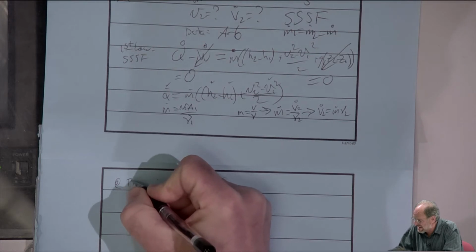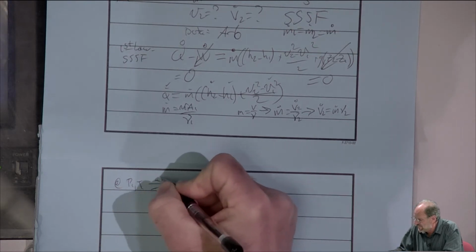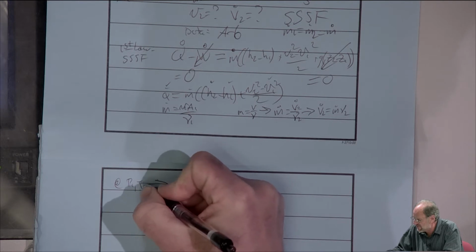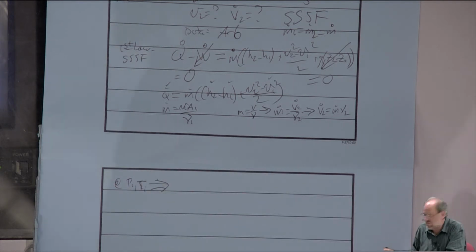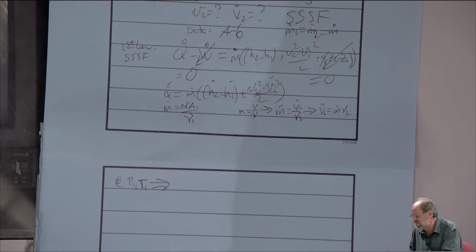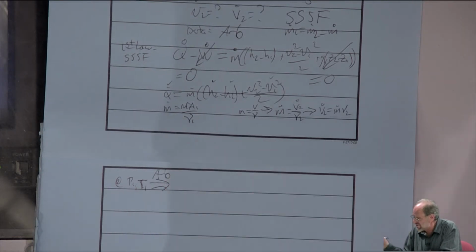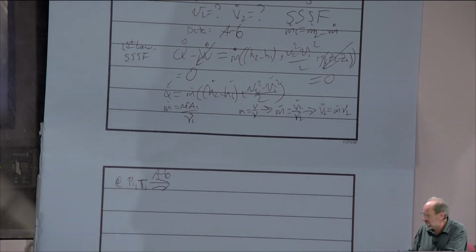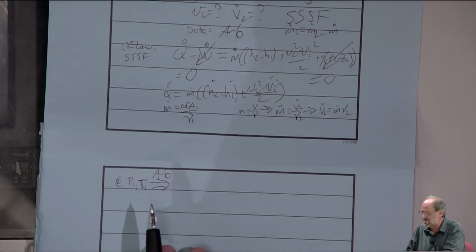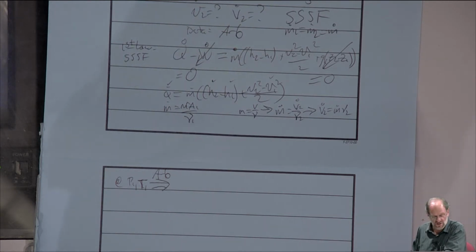We'll start at P1, T1. We're told that it's steam, although if you don't believe the author, or if the author just says water or H2O, you can do the usual check. At this particular temperature, the pressure is less than the saturation pressure, so it's superheated. Or at this pressure, the temperature is greater than the saturation temperature, so it's superheated. Either way you do it, it's still superheated. Or you can use what I call a brute force method, just hunt around the tables, and eventually you'll find the right property data. I would much rather you do that little test and know which table to use so you don't waste 5 or 10 minutes just trying to find your data.